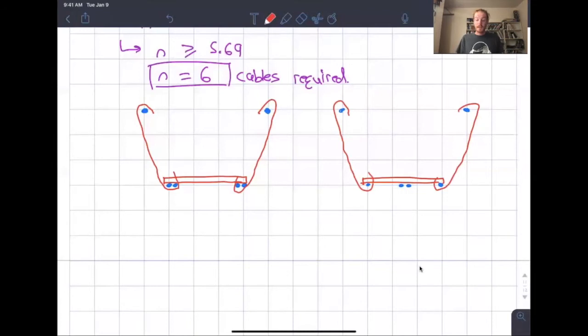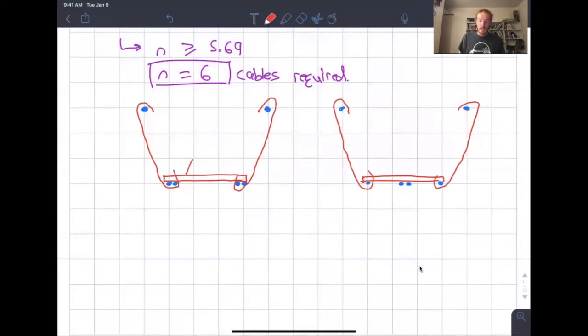something like that. But now we need to recognize that these cable configurations depend upon the type of crossbeam we're using. In order to have only cables at the edges and to not have a center cable, we need to be using steel crossbeams, because that's one of the requirements of our walkway analysis. If we're using wood crossbeams, we would use this other geometry.